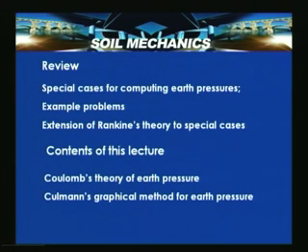In this lecture, we are going to introduce another theory called Coulomb's earth pressure theory, and subsequently we look into the graphical method for solving or computing earth pressure. This is by using the trial wedge method, which is also popularly known as Coulomb's method.